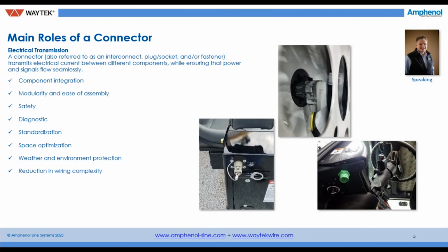When you think of component integration, the combination of electrical components into a functional electrical system, modularity and ease of assembly is important. Examples would include the capability to expand position counts, either with power or signal. Safety, it could be specific to a standard such as flame rating or even a dead front contact. Dead front contact is maybe where we put a polymer tip on it to keep individuals that may be touching those contacts from being harmed by the amperage. Safety, diagnostic. Example of diagnostic would be an integrated LED into a connector, which confirms signal or power is present.